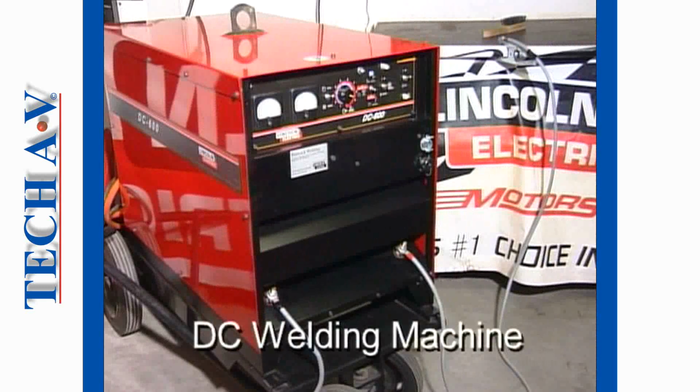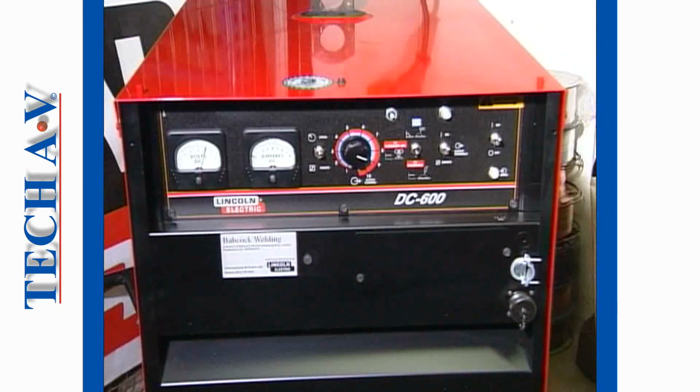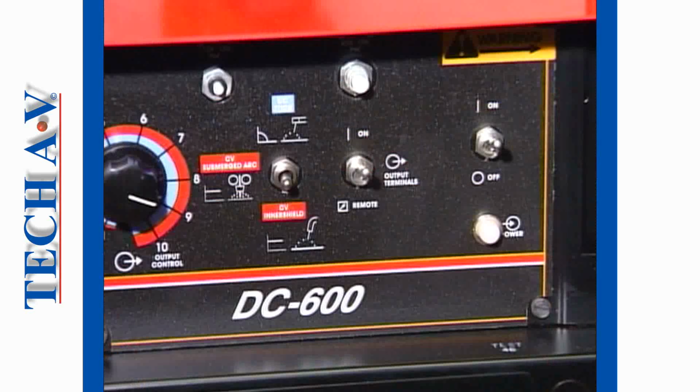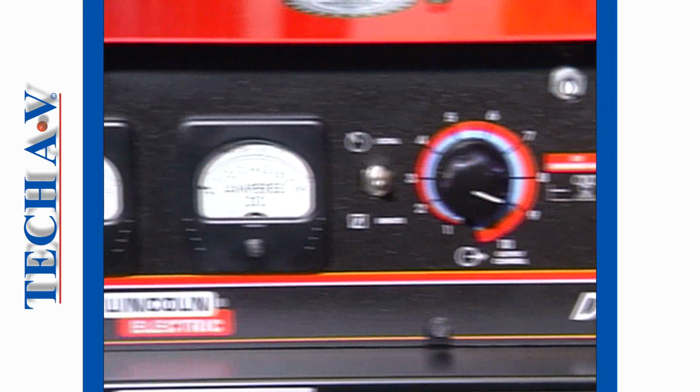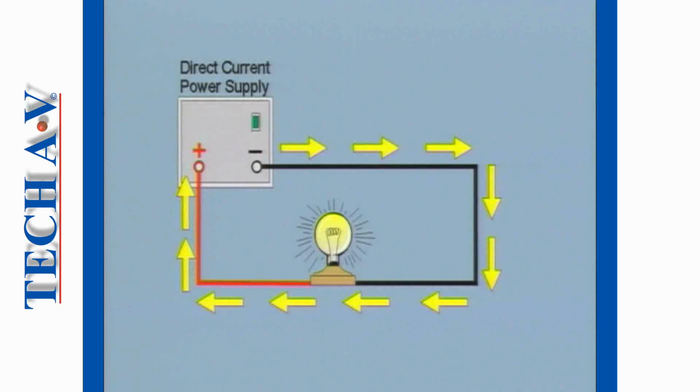Featured here is an example of a typical DC welding machine. Direct current is most suitable for welding thin steel plate, but is also used extensively in other industrial applications. Let us explain some important aspects about DC welding machines. In a DC circuit, the flow of electrons moves from a negative connection to a positive connection.